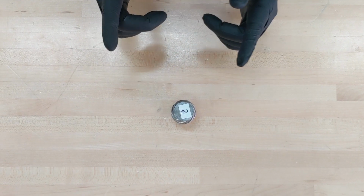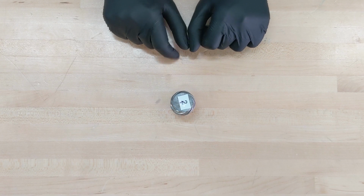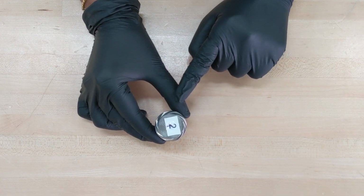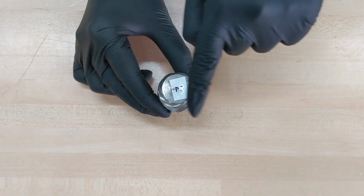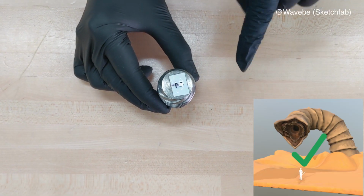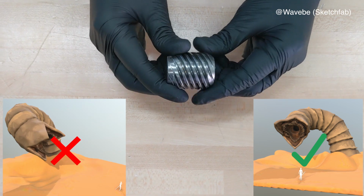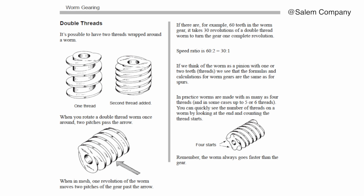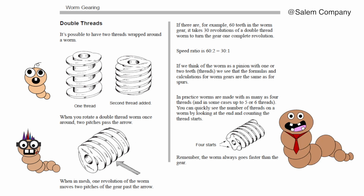Another quick note regarding the worm gear is the method by which one counts worm gear teeth. Remember, to count worm gear teeth, you should look at the front of the worm rather than the side, which is where a worm's teeth are easiest to count. In the following diagram, worms with 1, 2, and 4 teeth are shown. Keep in mind, when running with this transmission, that the worm always spins faster than the gear.